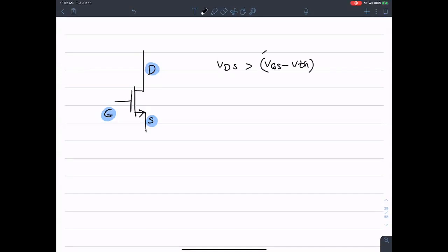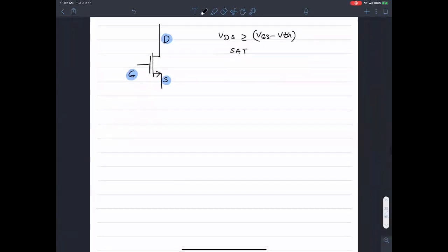this is also called overdrive voltage or on voltage, and a bunch of different names, VDS SAT. Okay, if the drain voltage is greater than or equal to the gate, then you know for a fact that it is in saturation. Let's say here is my gate, that's my gate voltage. The drain needs to be up here. That's where the drain needs to be. If the drain is equal to the gate, that's still in saturation.